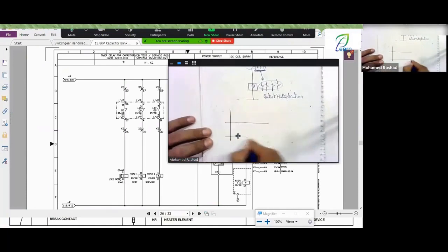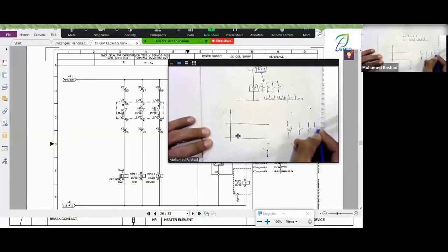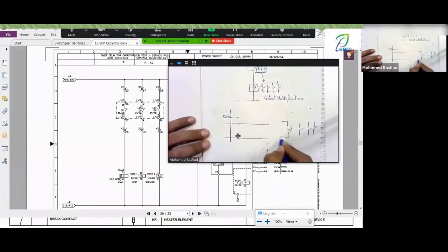This timer is like a coil with a set of switches, okay? Like normal open and normal close. Okay, what is this timer? If you apply a 125 volt DC supply to it, very nice. This is the supply you put on this coil. As soon as you apply the supply, does it change the contact positions? No. What does it do? It counts a delay time.